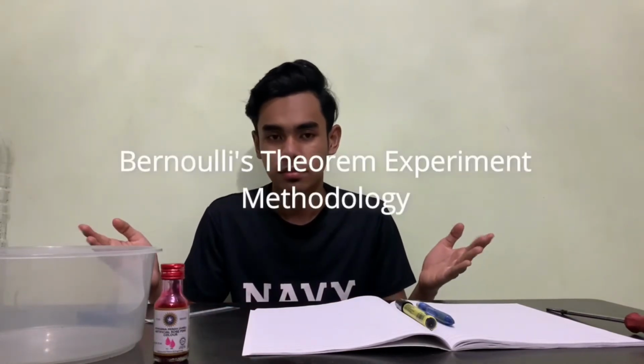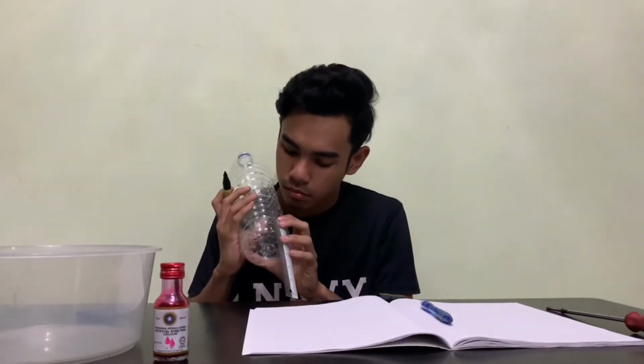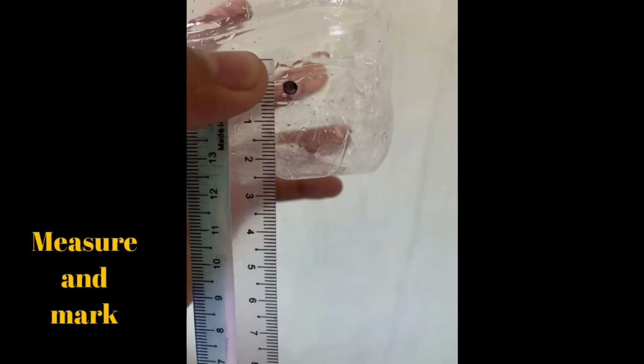Hi, next I will be talking about the methodology or the procedure of this experiment. First, take an empty bottle and make sure that it is empty. Next, by using the marker and the ruler, measure from the bottom of the bottle the length of 2.5 cm and mark it. After that, heat up a screw with a heat source, and then push the hot screw through the plastic bottle to make a small hole or orifice at the mark point.